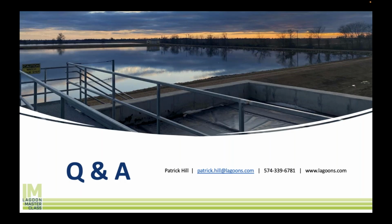I understand that barley straw needs to be added before the warm season starts. When is that? And also, doesn't that barley straw add more solids to the lagoon? It does, and that's one of the downsides of barley straw, is that it adds some solids to the lagoon. When to apply it is really going to depend on your local climate and when you typically see your algae blooming.